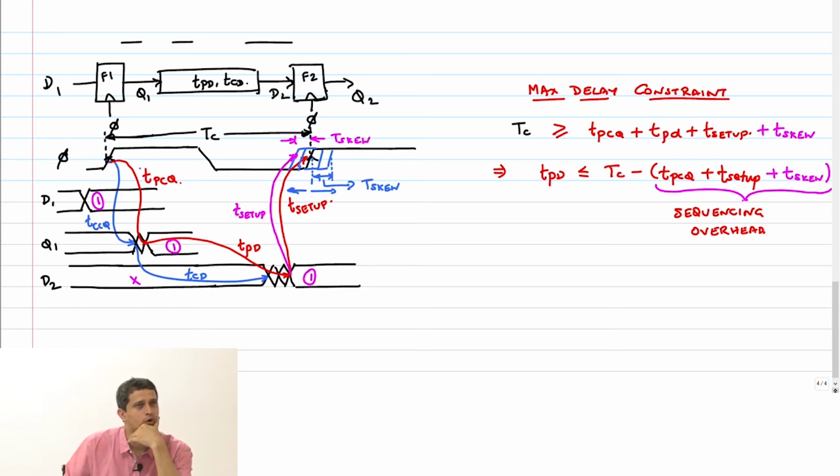So question is, should you count it twice or not? Exactly. So it's just a question of counting it as which one you take as a reference, that's all. And T skew I think it just boils down to what you define as T skew, right? That worst case number is with respect to one reference clock, where do these edges move, right?